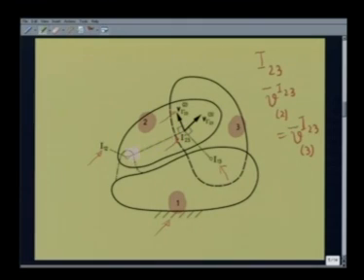This is the line I12, I23, then the velocity of this point as a point on body 2, which is rotating about this point, must be in this direction perpendicular to this line. But if I consider this point to be a point on body 3, which is rotating at this instant about I13, then the velocity must be perpendicular to this line joining I13 and I23, that is in this direction.